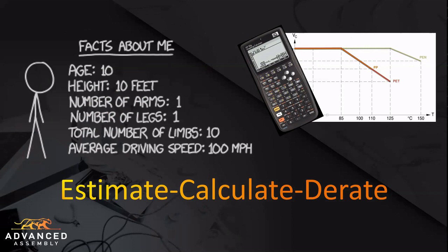If your budget doesn't allow for a fancy simulation software package, you're going to ultimately have to estimate and calculate your trace thickness. Estimation is often good enough for simple designs if you can give yourself a suitable margin for error by derating your design based on expected operating conditions.